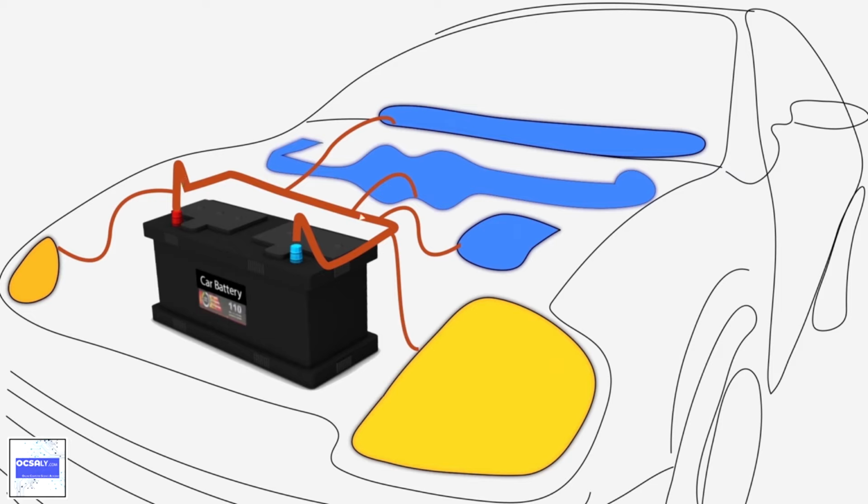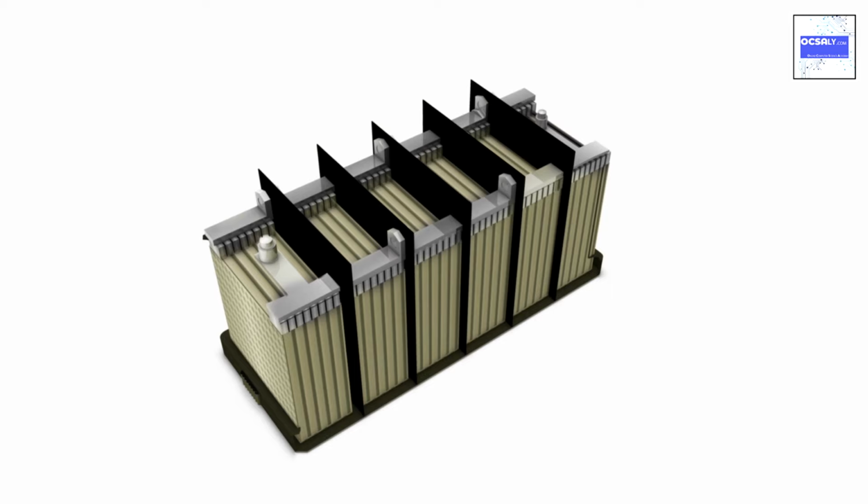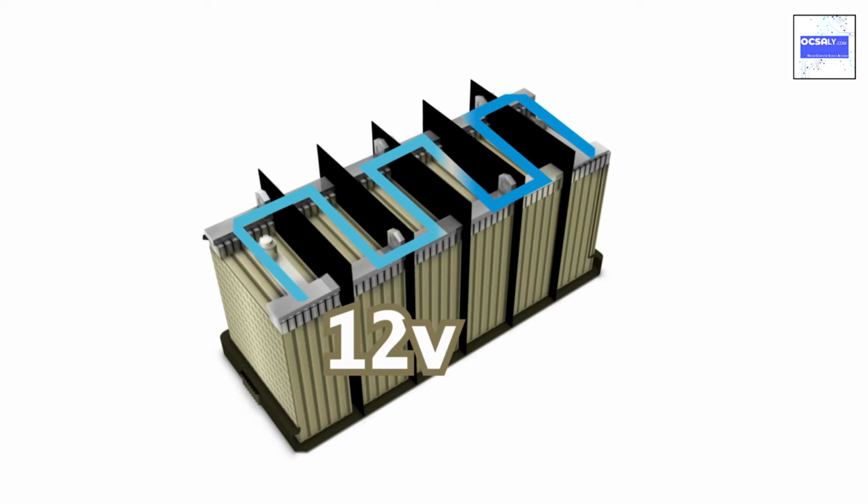the battery. The hydrometer is color-coded. A green color indicates that the battery is charged and serviceable. A green-black or black color indicates the battery requires recharging. A yellow color indicates that the battery is faulty. Where a yellow hydrometer is showing, the battery should not be recharged or tested, and the use of jump leads for starting should not be carried out. A new battery should be fitted and the alternator checked for correct operation.